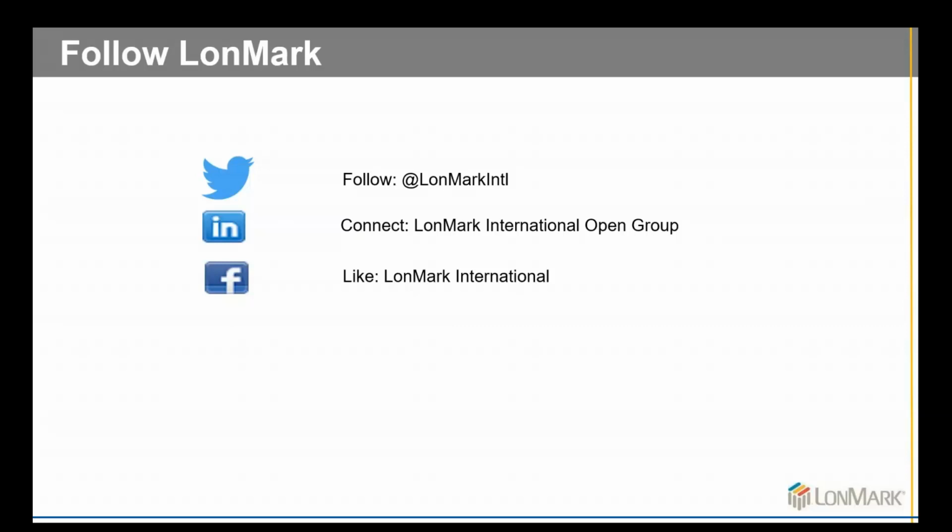they're finding that the older, the legacy power line communication technologies like the narrowband and G3 and Prime, they don't have enough bandwidth to handle the security requirements. As an example, in Germany, I know that they couldn't qualify those technologies purely due to security concerns. Now, with HD-PLC and broadband technology, you have the bandwidth to add all the additional security.